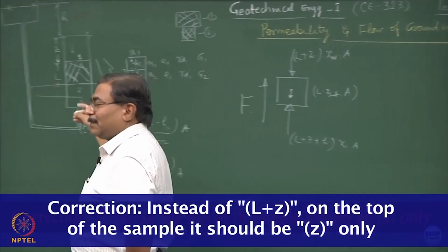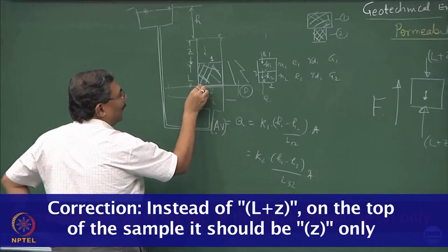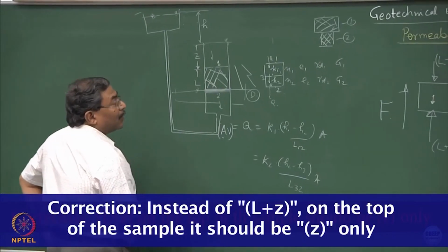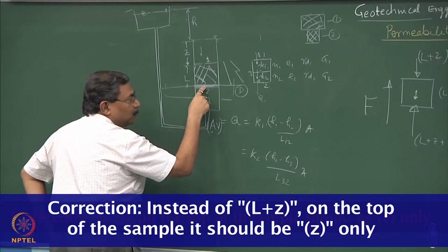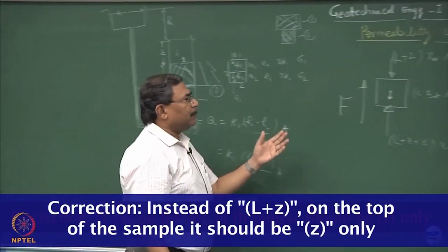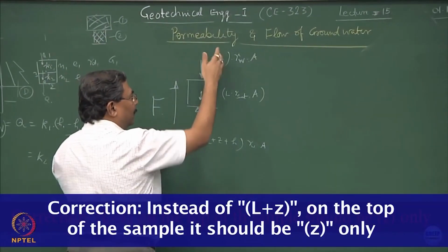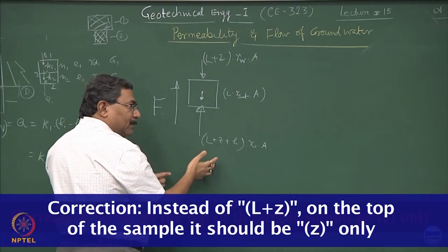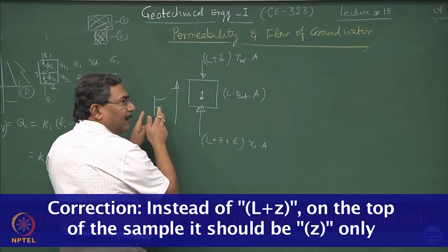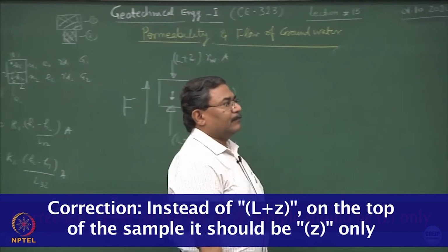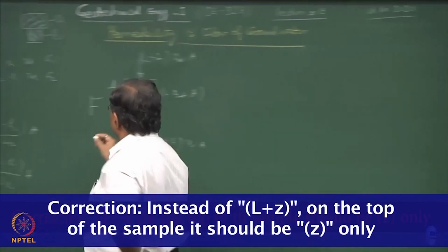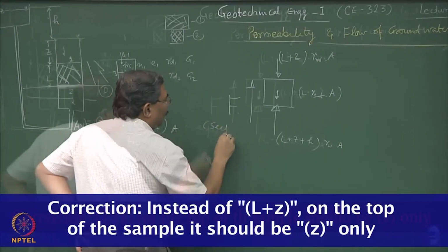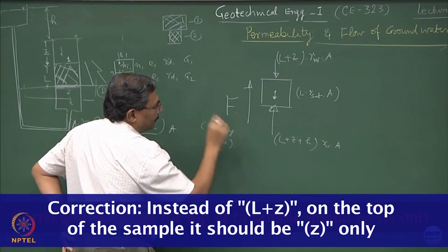Wherever your datum is at this point. Why? Because the entire pressure head and elevation head is acting at this point. Clear? So, truly speaking, what is happening? You have 1, 2, 3 forces and they are being balanced by F, and this is what is known as seepage force.